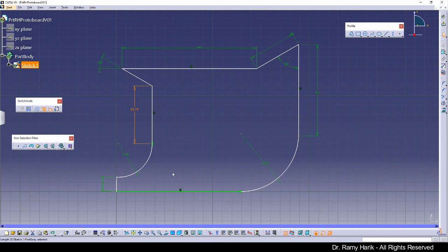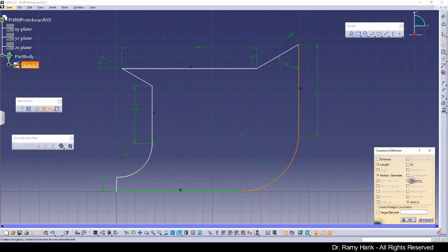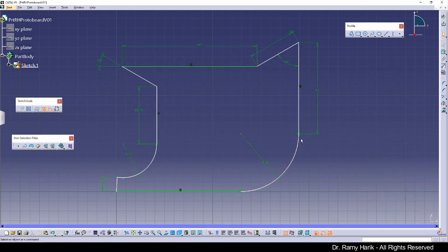So it is starting to get shape. Let's see, what did we forget from the first stage? We have, oh, tangency in here is missing, so we have to make sure that we have tangency or it will break up. So we have tangency, we have a radius of 60, that's good. We have a first dimension 60, 95, 60, 50.